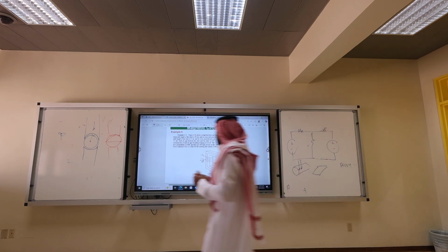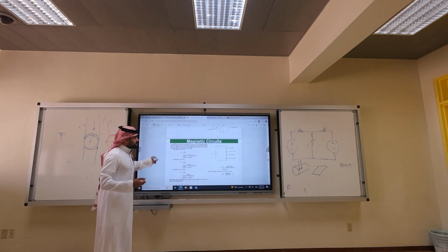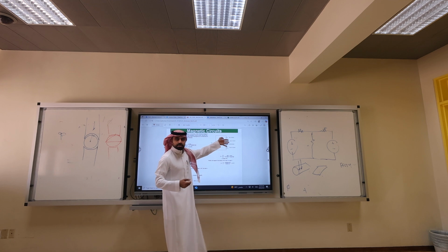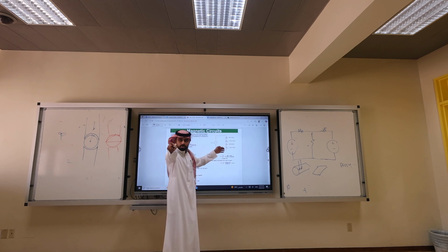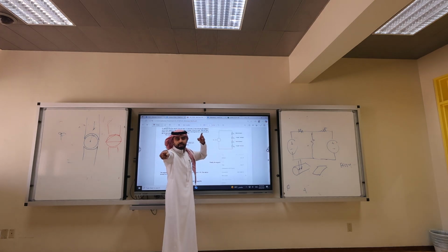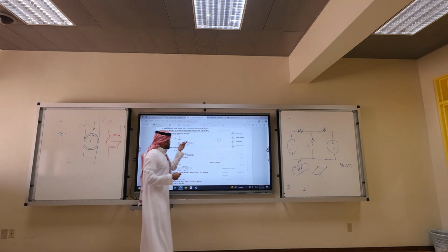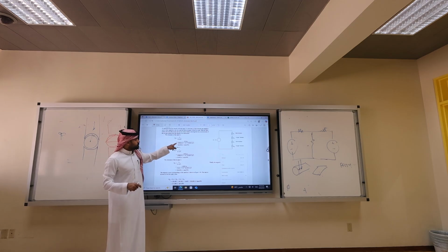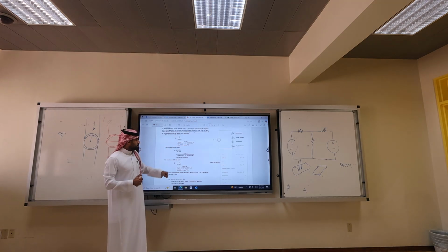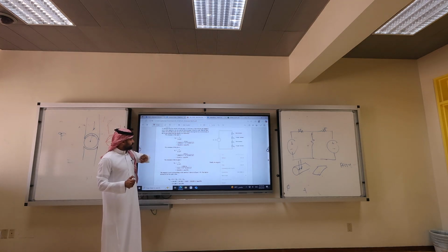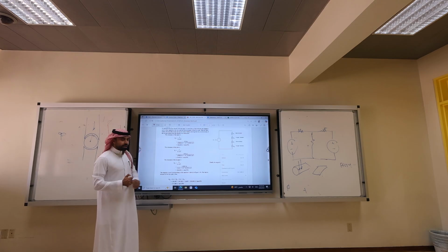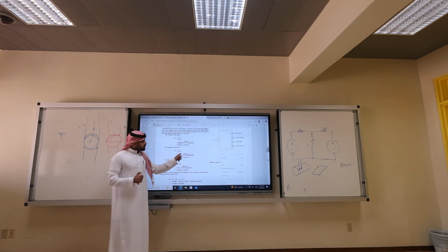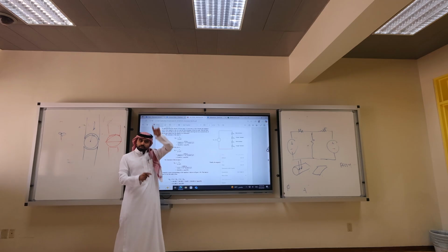Now, this is the equivalent circuit. 4 reluctances, or you can have 3 reluctances if you combine the 2 air gaps. Reluctance 1 is for the core, which is 0.5 over 2000 mu naught times 12 centimeters square converted to meter, which is 166,000. Reluctance of the rotor is 0.05, the diameter of the rotor.